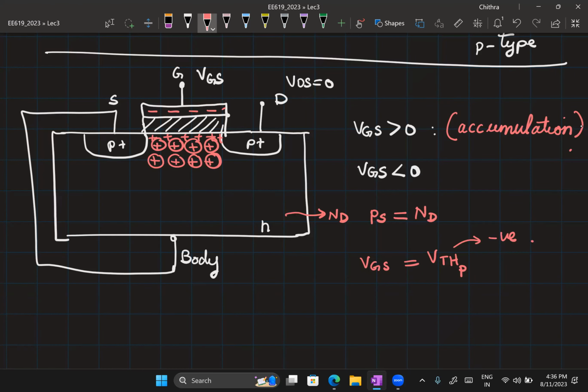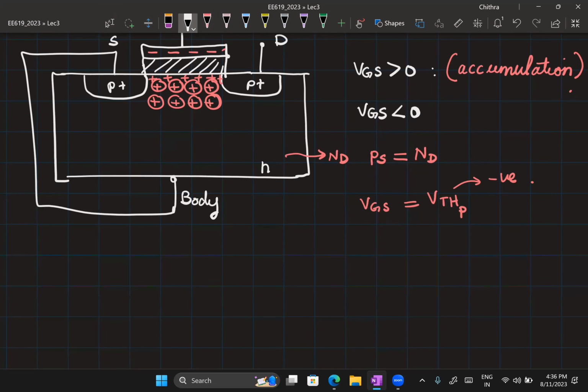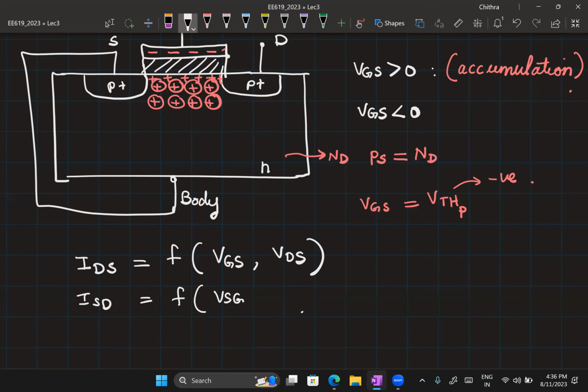So now rest of the transistor equations, we can easily compare it with the NMOS transistor and derive. So I have a comment to make here. You could be writing your IDS equations as a function of both VGS or VDS, and of course all the other parameters, or you can write your ISD as a function of VSG, VSD, etc. I mean, you can think of other combinations as well, but these are the two popular conventions in which we write the PMOS current equations.